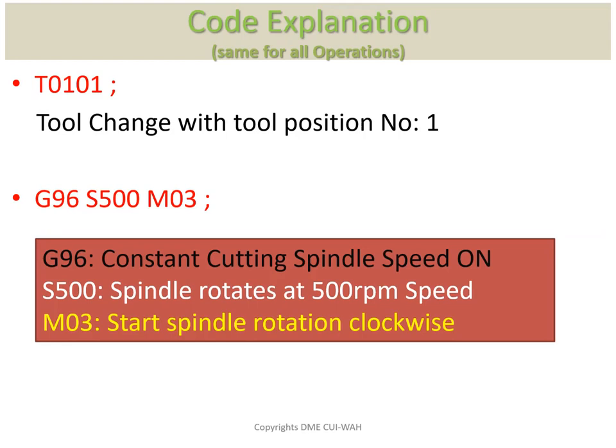Now starting with the next command, this was T0101. Normally T command is used for changing of tool. As we have discussed earlier, there are a number of tools, almost 4 tools can be applied at different tool posts. So T command is used for changing of tool. Here the first two digits 01 represent tool number 1, and the second 01 represents the offset number. It means we have tool number 1 at one position. I am calling my tool which I have numbered in number 1 position to offset number 1 for the facing operation.